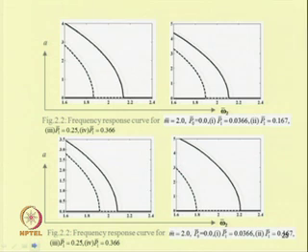Okay. Now one can see the frequency response curve when omega 2 is nearly equal to 2. When omega 2 is nearly equal to 2, the system will have principal parametric resonance. In this case, one can observe that the trivial state becomes unstable due to a pitchfork bifurcation while sweeping up.